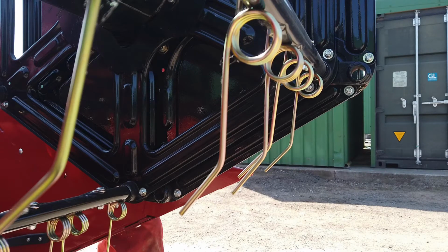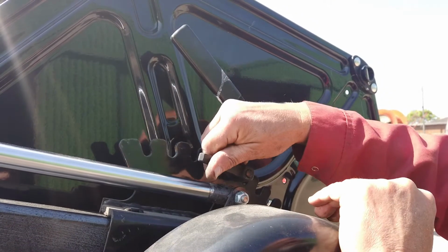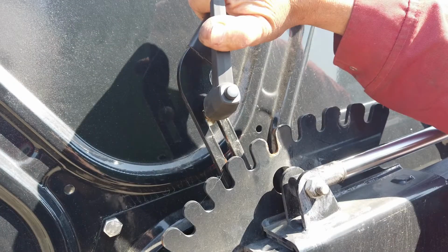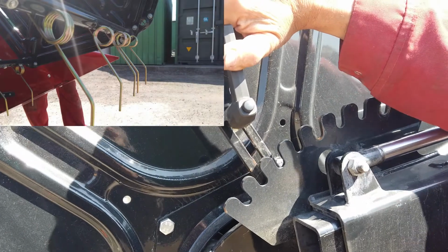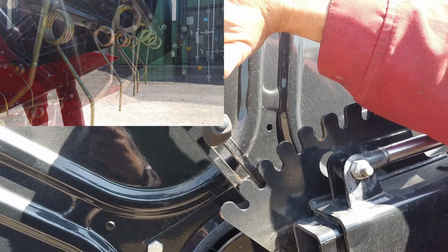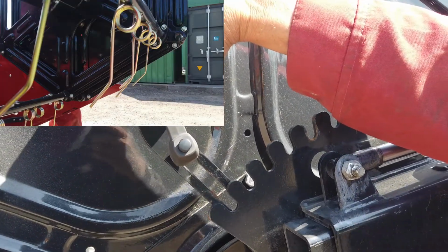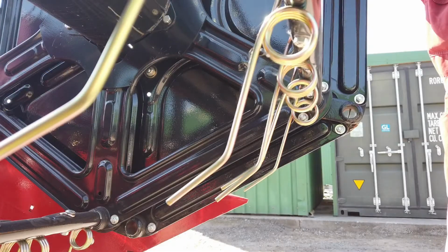This can easily be adjusted by positioning the selector in one of 9 positions. Ensure the handle is pointing rearward after tightening. In laid material, it is possible to use the reel as a pickup. Position the tines in position 1 and lower the reel fully to just above the ground level but below the knife. Some drivers prefer this method instead of crop lifters.